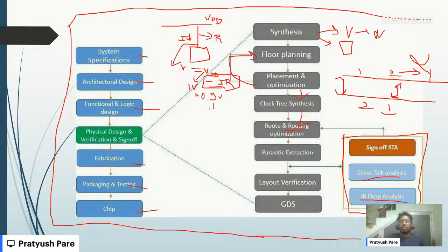And due to this change in voltage, मेरा जो IP के अंदर के कंपोनेंट हैं वो भी 0.9 वोल्ट पे चलेंगे. And as you know कि जैसे ही वोल्टेज कम होगा the speed will reduce, है ना? And the speed will reduce, तो भाई मेरा टाइमिंग खराब हो जाएगा, everything will break down eventually.